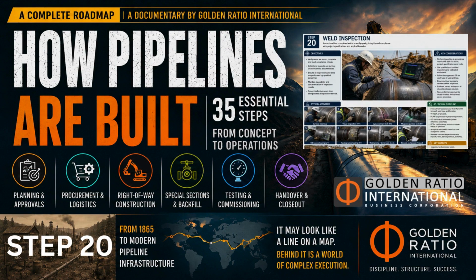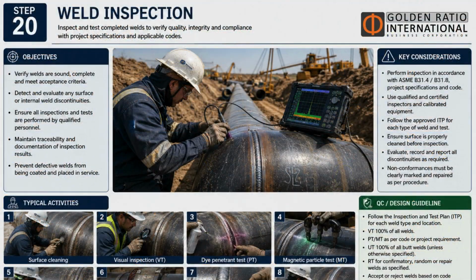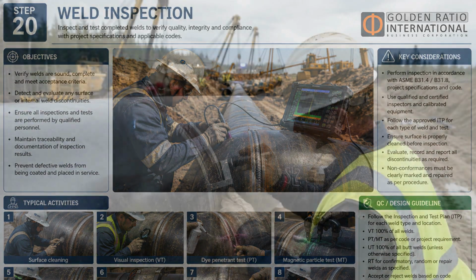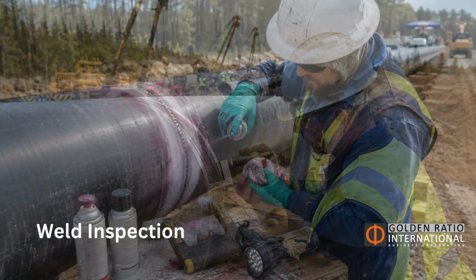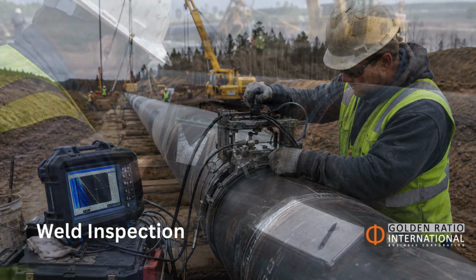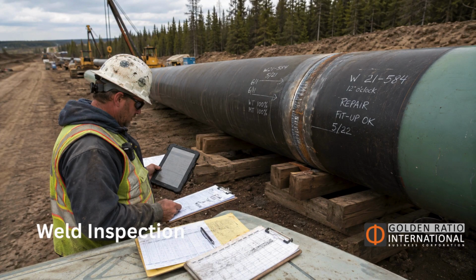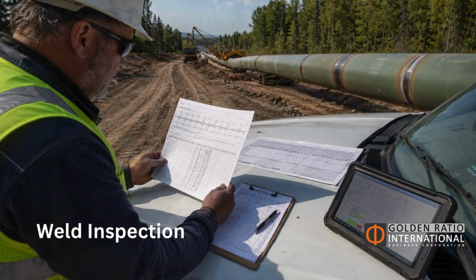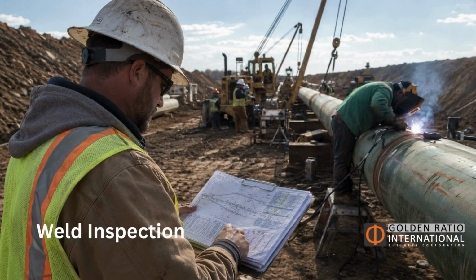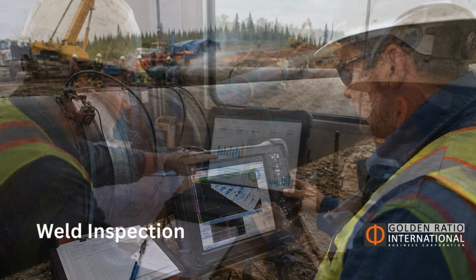Weld inspection. After welding, the welds must be inspected to confirm that they meet the required code, specification, and project quality standards. Inspection may include visual inspection, non-destructive examination, radiography, ultrasonic testing, weld mapping, and repair tracking. Rejected welds must be repaired and re-inspected before the work can continue. Inspection results affect production because coating, trenching, lowering in, and backfilling depend on accepted welds.